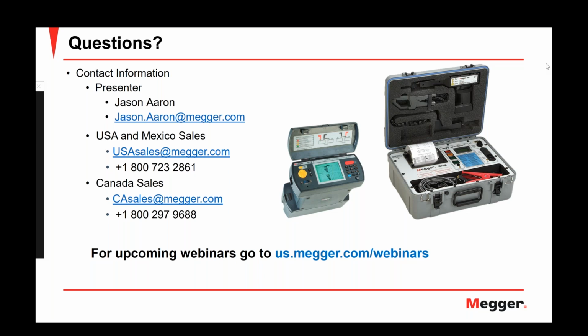So you could have false positives or false negatives, where the battery is already dead and the impedance doesn't change, because of the way the chemistry happens. So it's a matter of understanding the battery, understanding the results, and developing your own analysis method. For lead acid batteries, it's more developed, and we have some reference values to analyze the results. That's why it's more applicable to lead acid batteries.